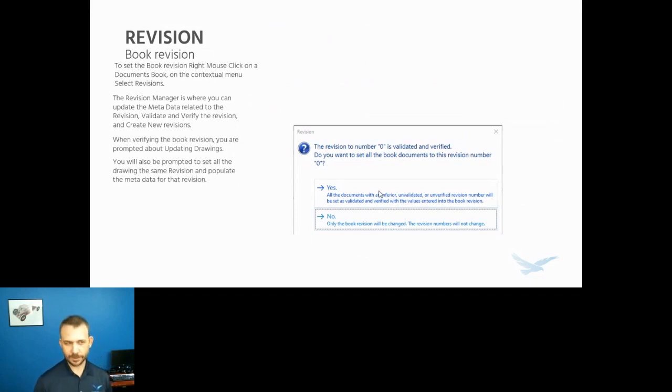The other thing you've got to think about is the integration between everything inside of SOLIDWORKS Electrical, right? As everything is touched or connected to the database, there's no real drawing in the background for that information. So if you think of a SOLIDWORKS Electrical document book as a multi-sheet SOLIDWORKS drawing, if you were to check that drawing into PDM and do revisions in PDM, you can't rev just page 1 of that drawing. Can't rev just page 10 of that drawing. You have to rev that whole drawing to the next revision.